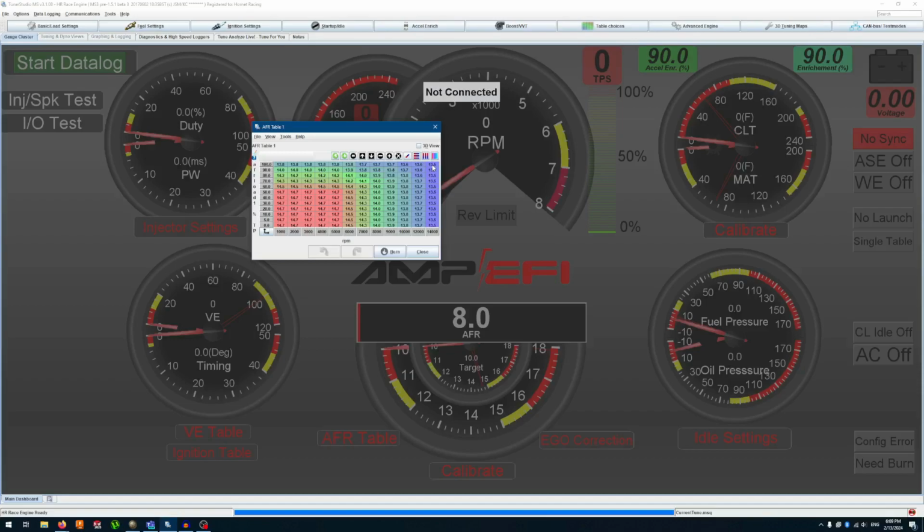The more you lean out, the less fuel you use, but the hotter you run. They say lean is mean, but there's more to it than that. It's not necessarily that simple. There's a lot more stuff to it if you read into it. But I wouldn't change this unless you know what you're doing. You certainly could at least try to lean it out a little bit. I'm sure I will try to lean it out a little bit to try and save fuel.